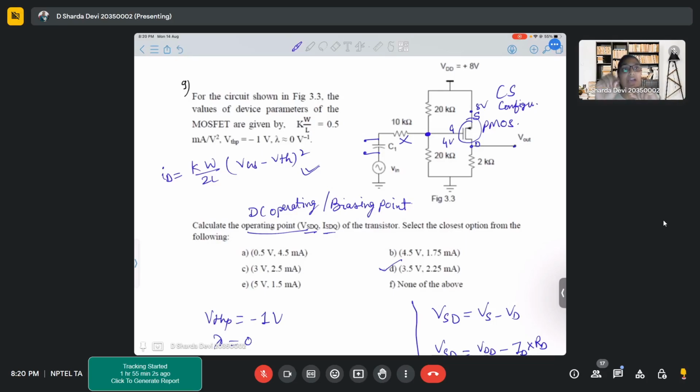At that time, you have to put your DC sources to AC ground. They are not truly ground, they are just AC ground to simplify your calculations, and you will find the output signal corresponding to your input AC. There you will not consider any DC. Am I clear?